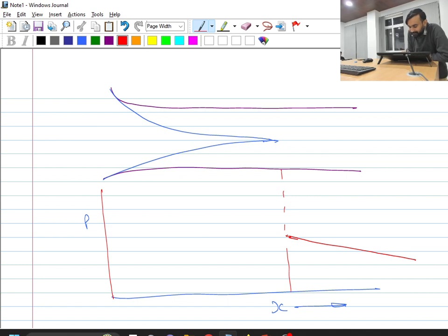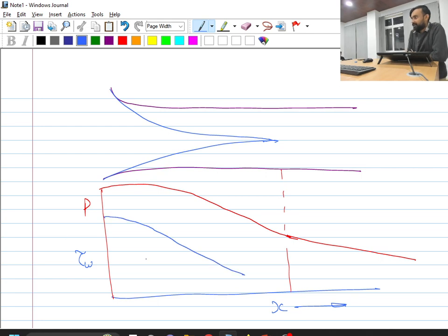Okay, but before this we will find some non-linear variation of the pressure in this region. So one clear idea is that, if I have to plot shear stress by some other line, let me represent this P with red color, and if I represent wall shear stress with blue color, then wall shear stress will also have a similar variation: it has some huge value in the starting and then it decreases, and after this point it will reach a constant value in the fully developed flow region.